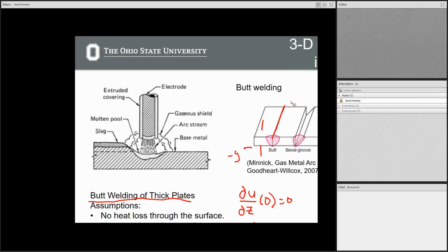So we would expect that the temperature prediction we're given is higher than it would be in reality, because both of these are heat loss mechanisms here. The infinite plate assumption assumes that this system can continually be heated in one location. It's always dissipated off to infinity, off to really far distances.